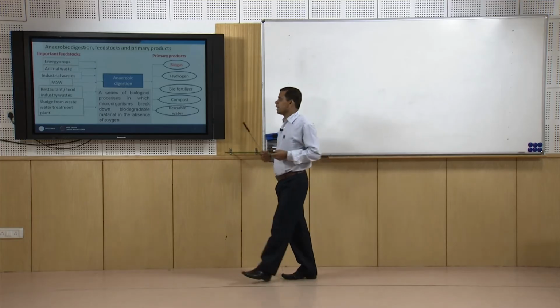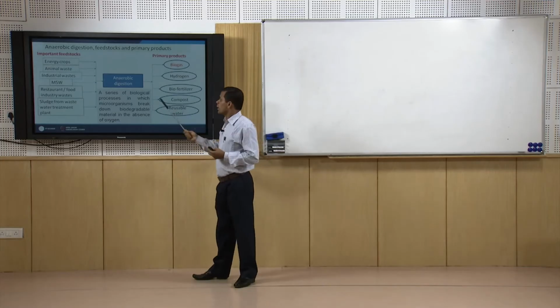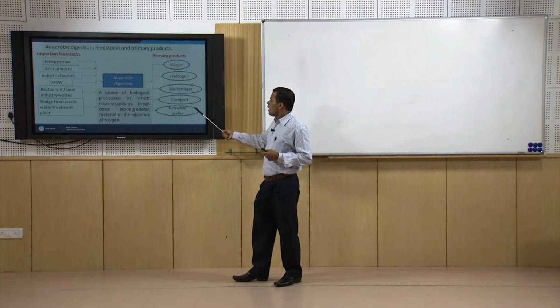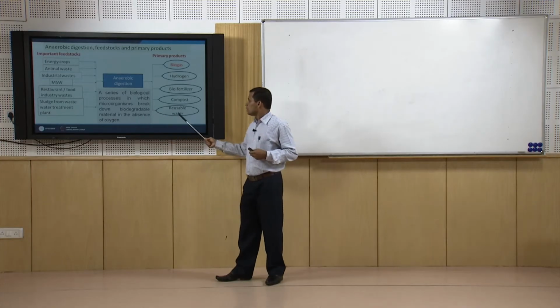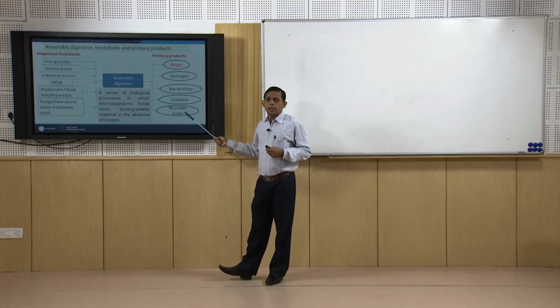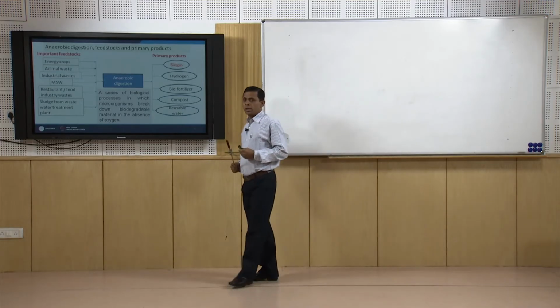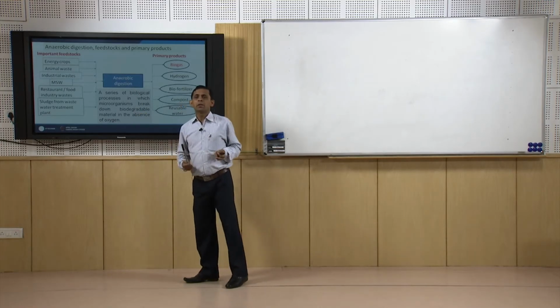So, the remaining 92% is liquid, but if we use a thermal route, then the moisture content should be very less. So, around 80% should be solid content. In this case we get a large amount of slurry. That slurry contains a significant amount of water, and that water has to be removed or reused, otherwise this process will not be acceptable from an environmental point of view.